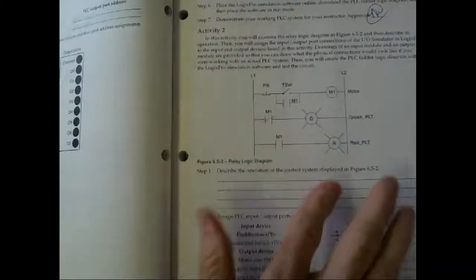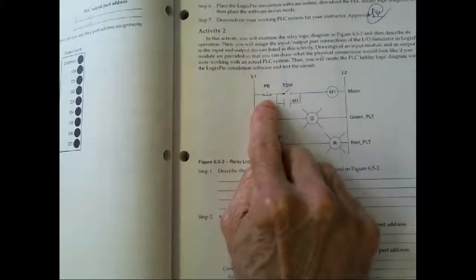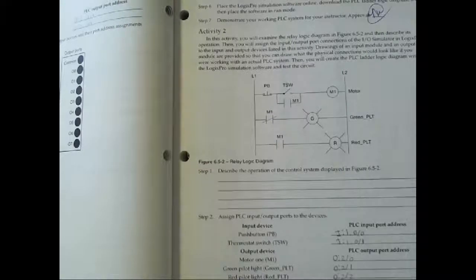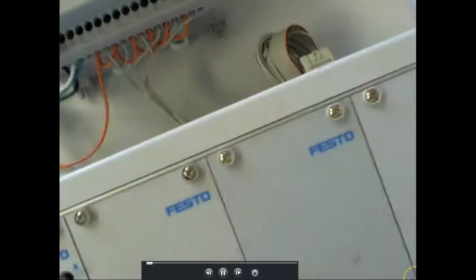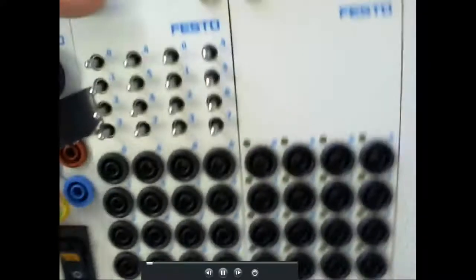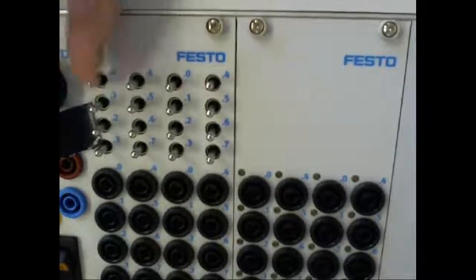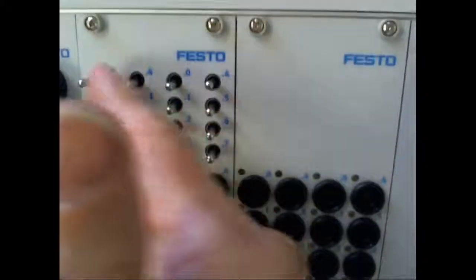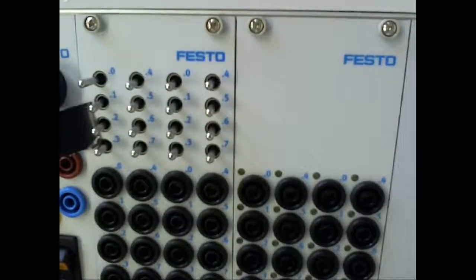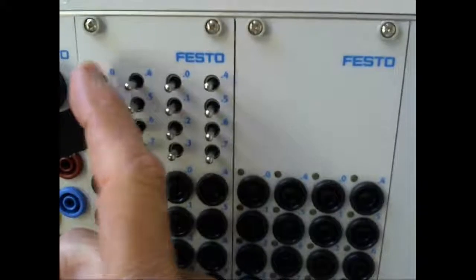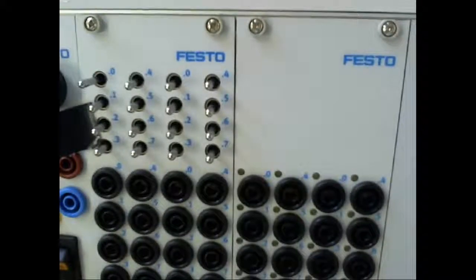So this one's pretty much the same, except we're going to use an examine if closed. Now, how do we get a normally closed switch? Well, on the 1100s, you just take one of these switches over here that you assigned and just put it in the on position all the time, and that makes it a normally closed switch, right? You understand that? Everybody understand that? So can y'all see I've got this one on all the time? That might be the